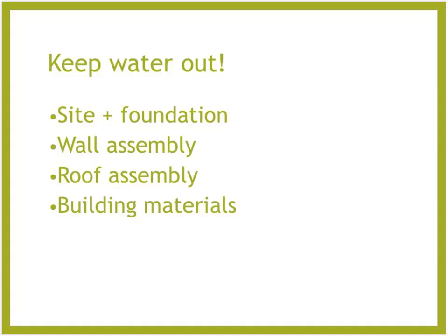And then if you're building a new home, recommending to not build a basement at all, because again, it can lead to a lot of issues. Just do a slab on grade. If there's flooding or what have you, the basement's the first place you go down and it's moldy, it's mildewy. Up here in Michigan, we've just got some nasty basements. So that's one thing to consider, doing that concrete moisture slab test, water testing.